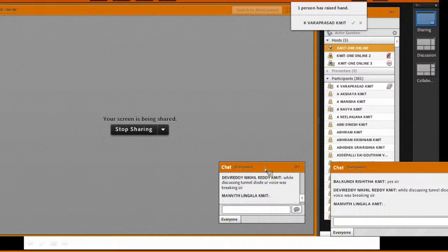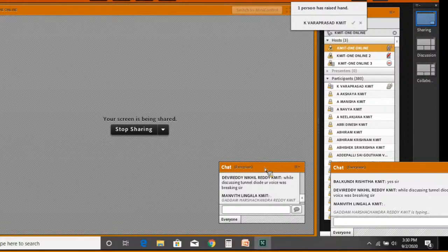Now, what is photoconductive mode? In the photoconductive mode, it is operating in the reverse bias configuration. During the reverse bias, if you are applying a smaller reverse voltage, it is going to operate according to that. The third one is the avalanche diode. What is that avalanche diode?